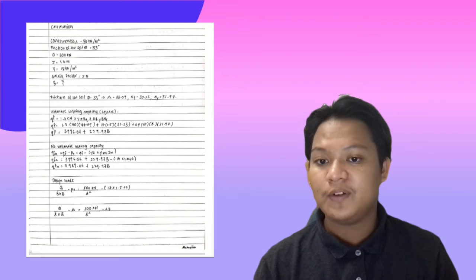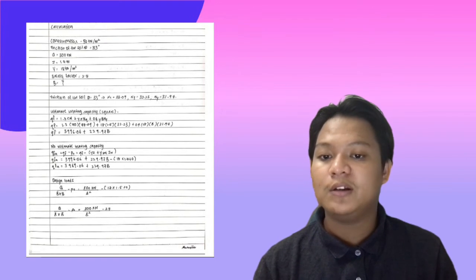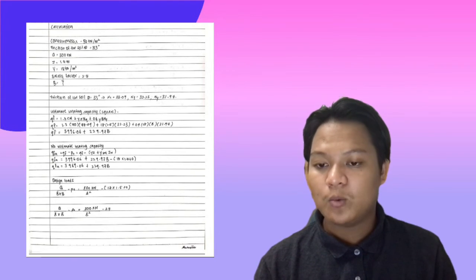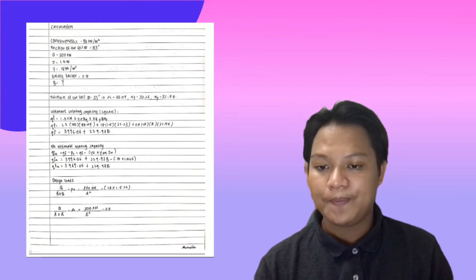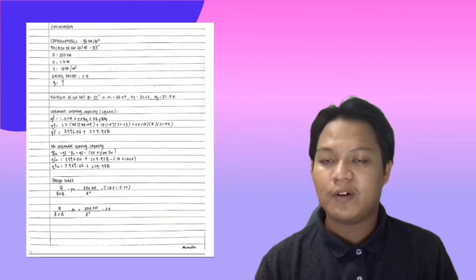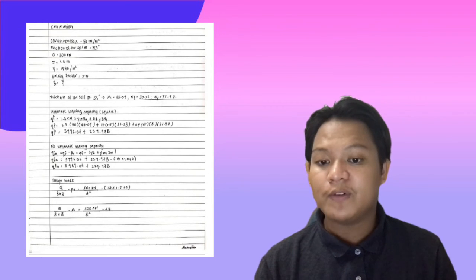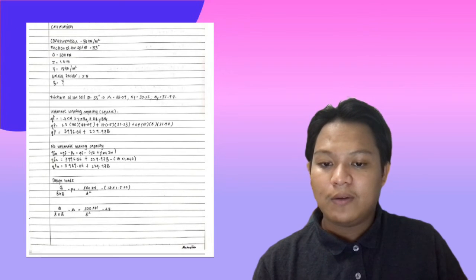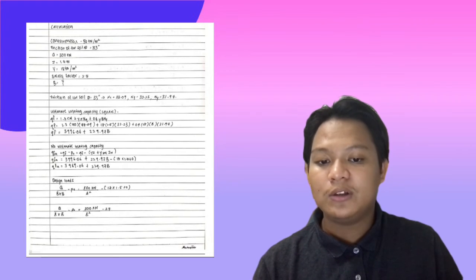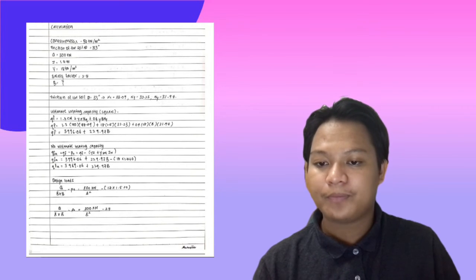So C is 50 kilonewton per meter square, the friction angle of the soil is 33, Q is 300 kilonewton, Z is 1.5 meter, gamma is 18 kilonewton per meter cube, safety factor is 2.5, and B is unknown. So the friction angle of soil 33 gives Nc 48.09, Nq 32.23, and Nγ 31.94.